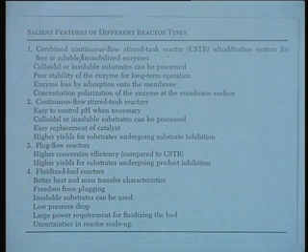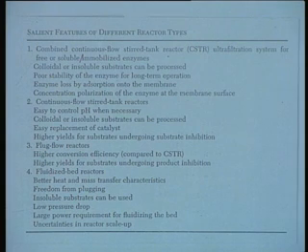Then of course, there is easy replacement of catalyst. In the case of a PFR, the regeneration of carrier is simple, because after the immobilized enzyme is exhausted, one can stop for a while, regenerate the carrier, re-immobilize the system and reuse. But if the carrier cannot be regenerated and it has to be replaced, the replacement of carrier is much simpler in the case of CSTR. And of course, we have talked about higher yields for reactions undergoing substrate inhibition.